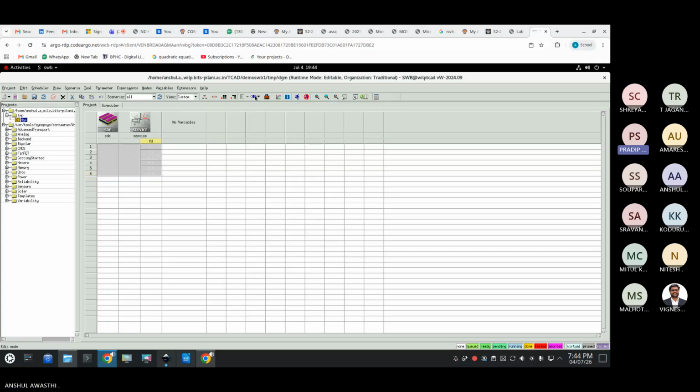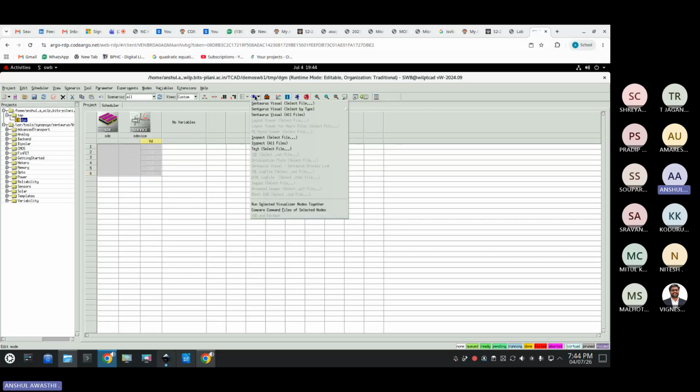For MOS devices, right? No, this code is for any device, whatever the device you construct. For any device, there will be gate voltage, drain voltage, and current. All three things. Verilog code is for simulation. Whatever the LUT you have made, it will be based on whatever the VDS, VGS, and ID is for your device, whatever the device you have constructed. I'll show you once.